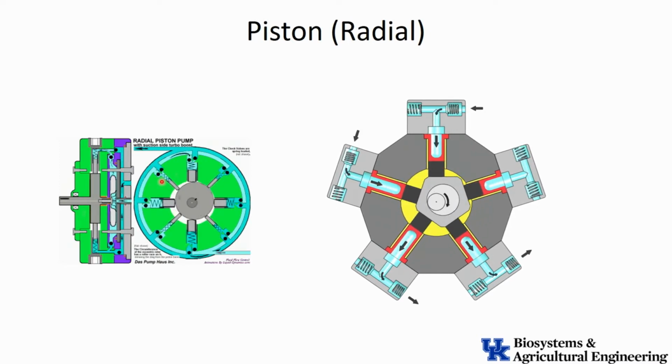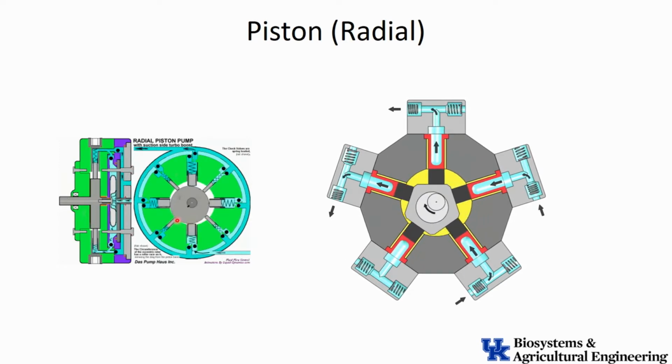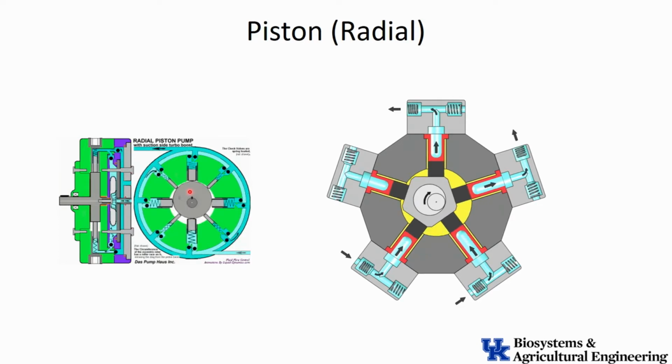Now, the interesting thing we can do with these is to port, somehow we're going to port the output pressure, so the flow that's coming out of this thing, we're going to port it or bring it back into the inside chamber here. Now, why are we going to do that? Well, a couple reasons. This is a rotating part. It's a cam that's sliding on the bottom of these pistons and everything, so I need to provide some lubrication there so they don't wear out and so forth.